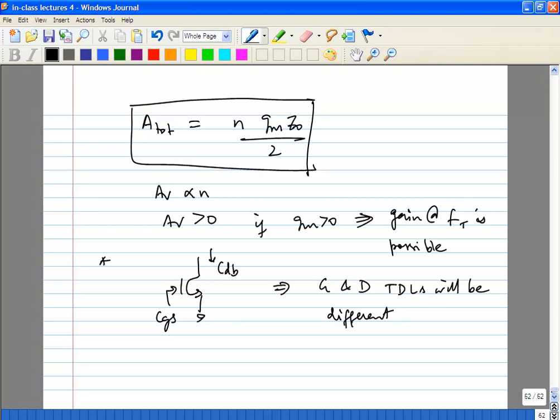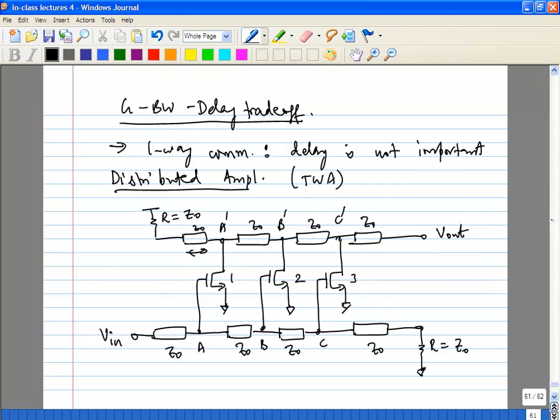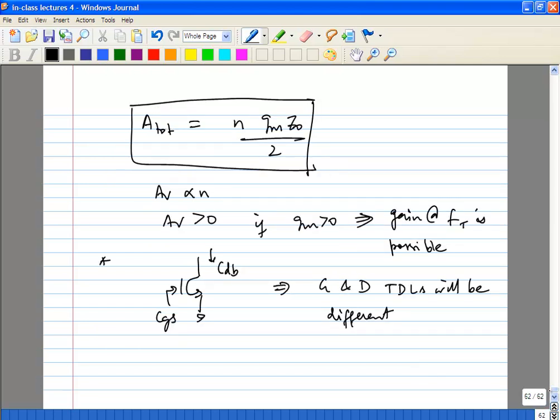In other words, you want a certain amount of delay. You want equal amounts of delay. If you use lumped LC quantities, they can give you enough delay that you need at the frequencies of interest. So you can actually use lumped LC sections for these transmission lines.